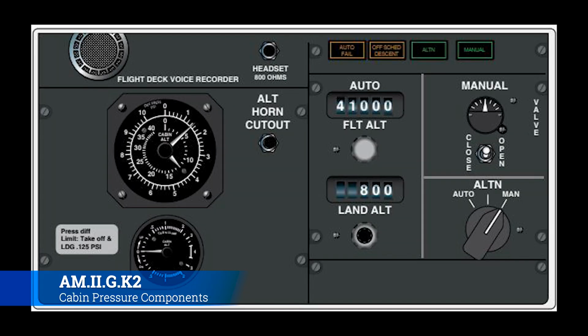Okay, so this is a graphic that shows you what a pressure controller might look like on a 737-800. Notice you have cabin altitude on your top left there, the big dial, and then you have a cabin climb, up or down. It's telling you what the rate of change is. Now you have a flight altitude that you're going to put it at. If they know what their cruise altitude is, they're going to make sure that's in there, so that the controller knows exactly where they should be. And then they have a landing altitude.